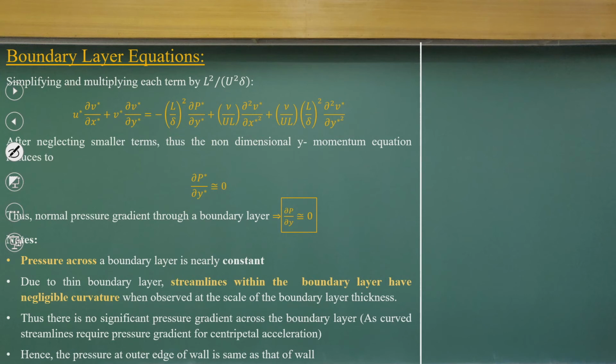That is what it is interpreting. If I draw it, I have the boundary layer, delta x is the boundary layer, and this is the wall or the surface. If you take a point P at x 1 and x 2, if you have a pressure P 1, as it does not vary along the y direction, everywhere should be the P 1 value.